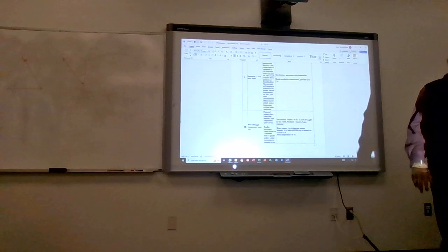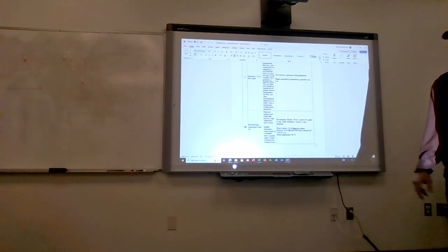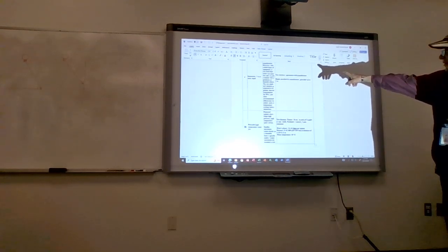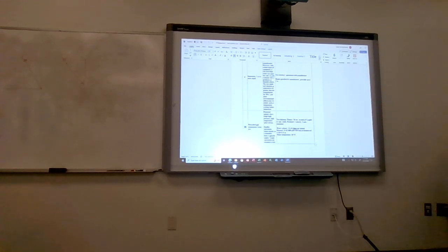You can actually put the luminaire in a pool that's 1 meter deep, and it would resist any water coming in. What about pool lights? Pool lights would have to be an IP68 rating. However, if it's at the bottom of a deep pool, we may have to go higher. So that rating has to go higher. And typically, a pool light will be a low voltage light, not a line voltage. Okay, so those are the IP ratings.